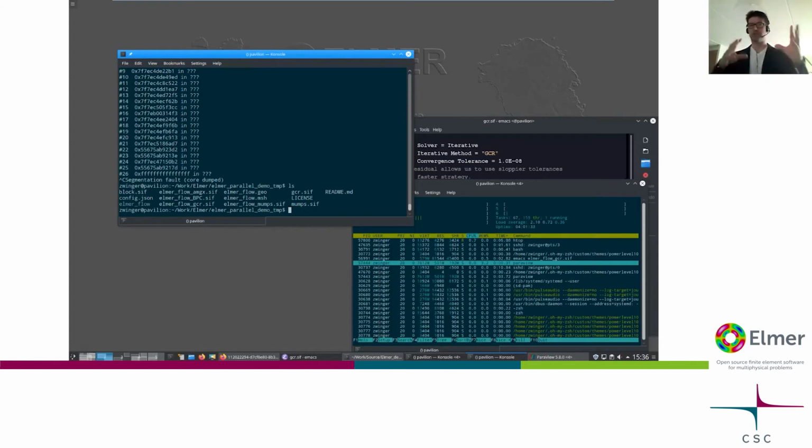And for that, you have to provide 6 mesh partitions where these solutions can be run on. And then we have to return back to the ElmerGrid command, and we want to change an already existing, namely Elmer flow grid, into a parallel grid. So we are doing ElmerGrid 2 2,